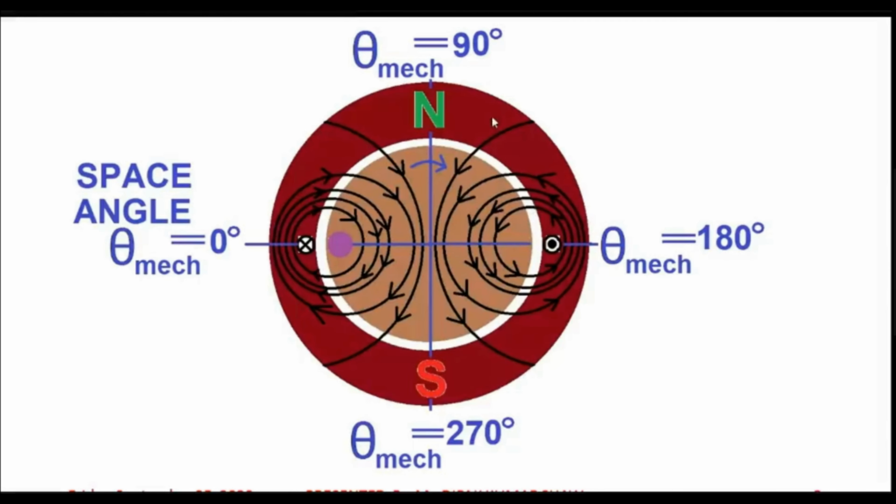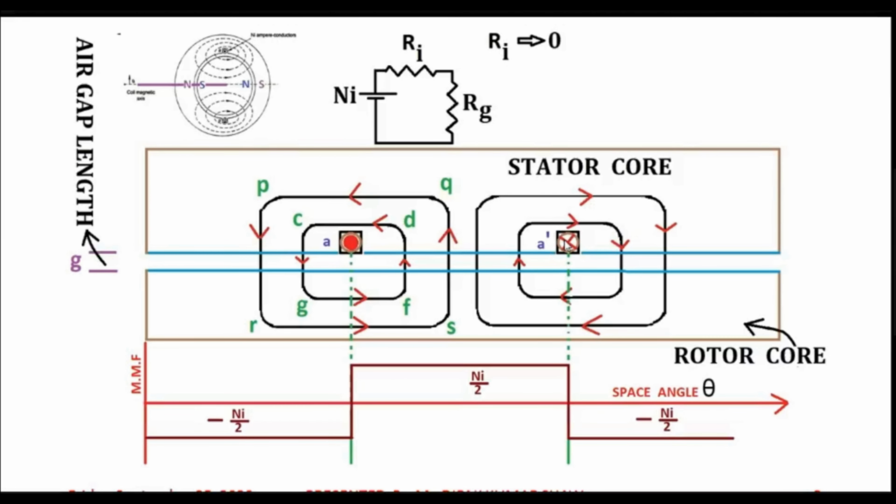a circle. And you can find that flux distribution, the magnetic flux distribution has been indicated for these two poles, that is one north pole and one south pole, which are developed on the stator core. And further what you will find that if you just apply Ampere's circuital law and take the developed view of the coil, and if you plot the space distribution of mmf, that is the magnetomotive force, it will come like this for a single coil.